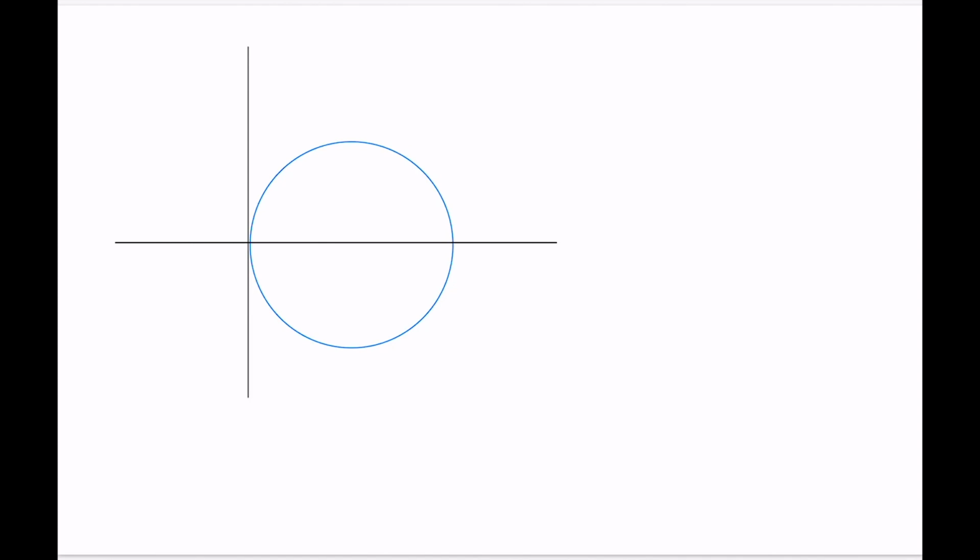Okay, so we had the center point of our circle, which was point C here, the reference point, which was point A, and the radius of the circle stretched from C to A. And our axes are labeled positive normal stress and positive shear stress pointing downwards. There we go.